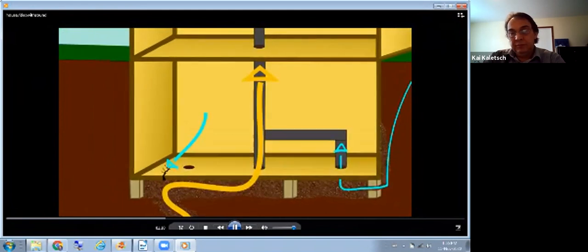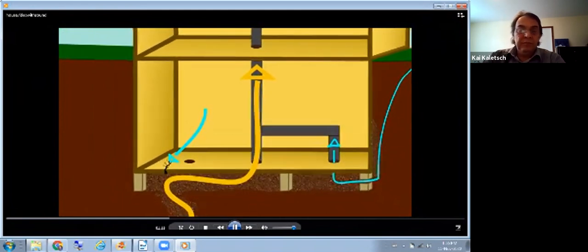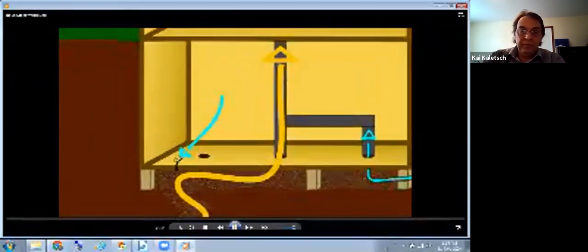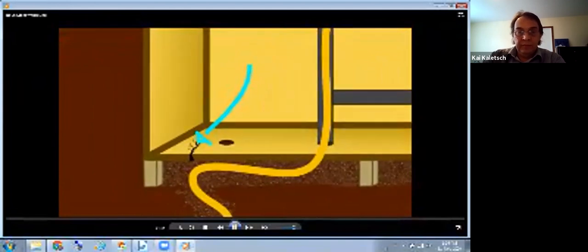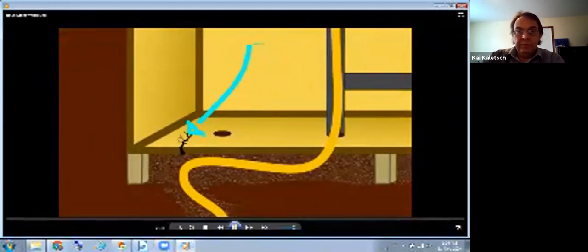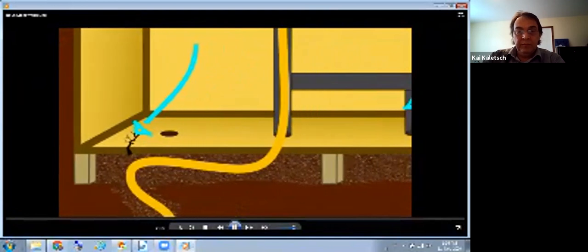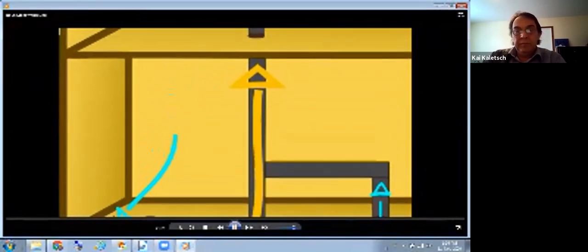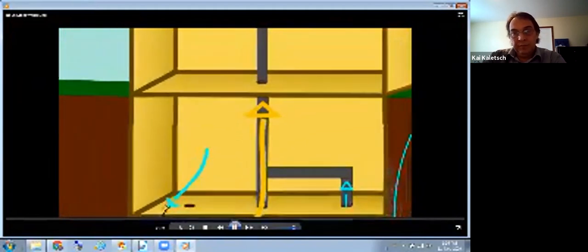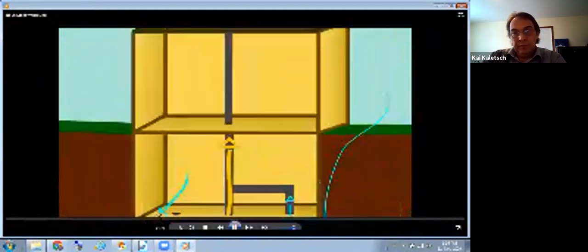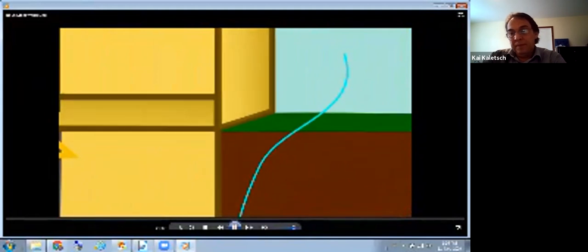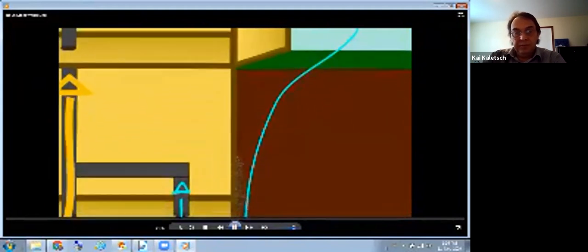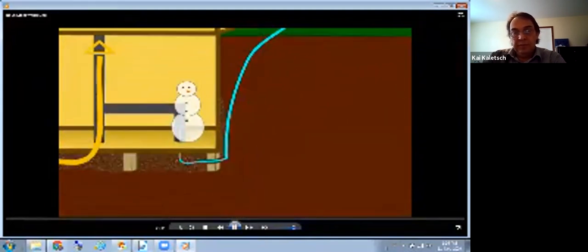To resolve this, the mitigator would run a jumper to a part of the slab where there was no communication. The theory is that radon is diverted from the crack and is exhausted. The flow through the crack is reversed and the basement air is drawn below the slab and exhausted with the radon fan. The problem with this method is that a lot of energy is wasted sucking in clean air from the outside, and in the winter this leads to cold walls and floors.